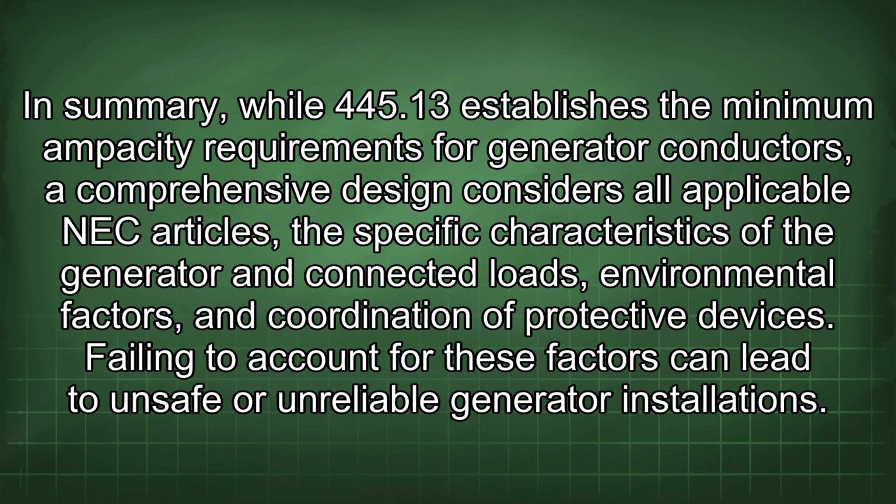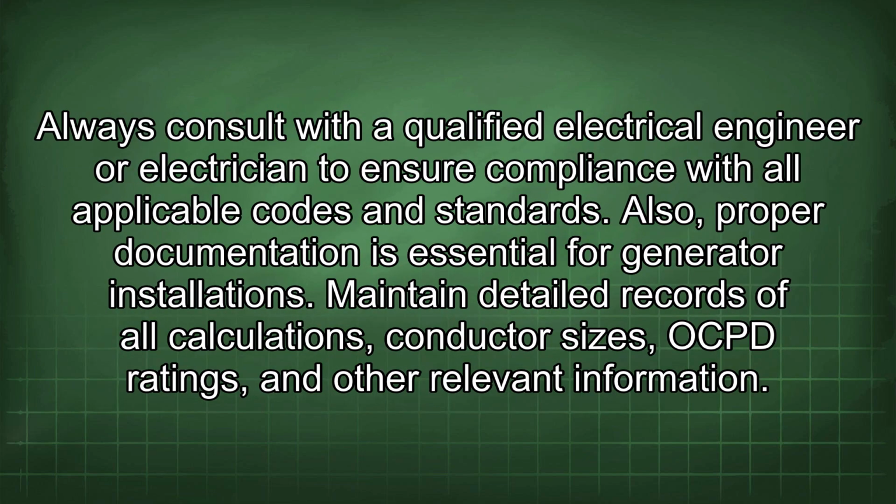In summary, while 445.13 establishes the minimum ampacity requirements for generator conductors, a comprehensive design considers all applicable NEC articles, the specific characteristics of the generator and connected loads, environmental factors, and coordination of protective devices. Failing to account for these factors can lead to unsafe or unreliable generator installation. Always consult with a qualified electrical engineer or electrician to ensure compliance with all applicable codes and standards.